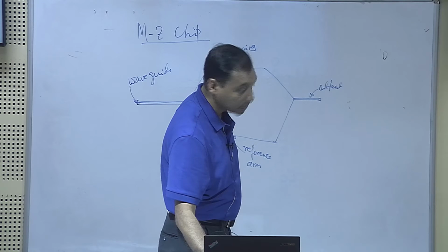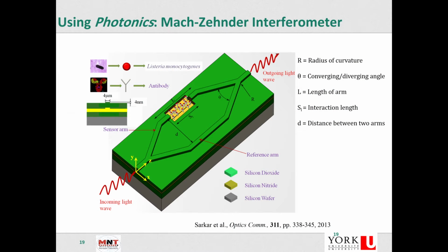Of course, as I mentioned, this kind of system, with any micro or nanofabrication process, is not a solution for limited-resource communities. It needs economies of scale. Why it is expensive is that if you look at the structure, the waveguide through which the wave propagates has a very unique structure. It has a ridge which is 4 microns wide with a height of 4 nanometers. This is an extremely difficult microfabrication or nanofabrication technique, because over 4 microns you have this 4 nanometers.